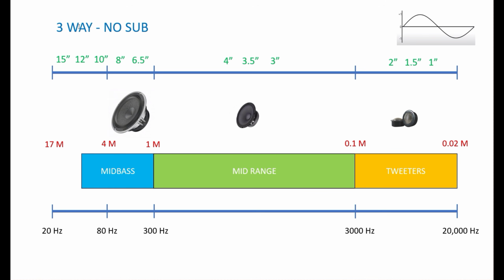Without a sub, it's going to be musical. It just won't have that super boomy low end, and you just got to be careful not to push your mid bass down too far, because it's going to reach the excursion limit, and if you do, it's going to sound boomy and terrible and distorted, and you're going to put your mid bass at risk of thermal damage, right?